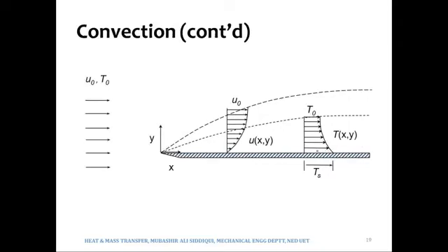So this is how the temperature profile would look like if Ts is greater than T infinity or T naught. We usually call it T infinity. So see what is happening with the temperature profile. The lengths of the arrows are constantly decreasing, for the same reason that I have mentioned. And then there would come a point where the temperature of a certain layer of fluid would approach T naught or T infinity. That region would be termed as thermal boundary layer.